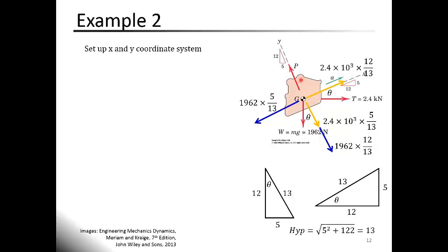And we have a reaction force between the car and the cable, which we call P. If we choose the X direction along the cable, and the Y direction perpendicular to the cable, all we need to do here is to resolve the forces along the X and Y direction. So we'll just resolve these forces as we go along.